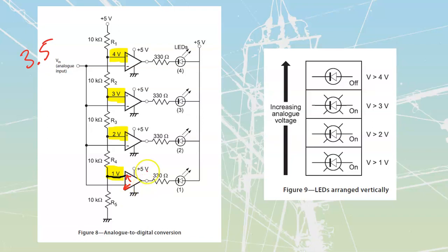And we do have to say which of my inputs I am coming into. If you take a look at that, you see that you're coming into the inverting input. The inverting input means that this thing is now going to switch out to a negative, or to the most negative point it can find in the circuit, which is going to be this ground that we're going to have over here. So let's compare our values of voltage. Right now we see this 3.5 gets fed to each of these. So over here I have got 3.5 compared to 1 volt. So when I compare these two, what am I going to see?